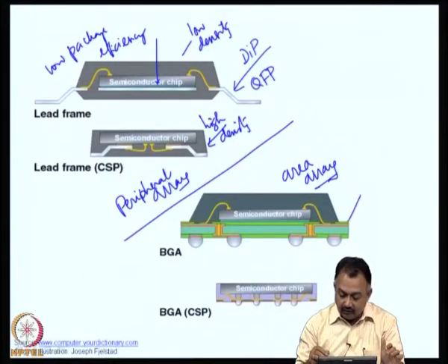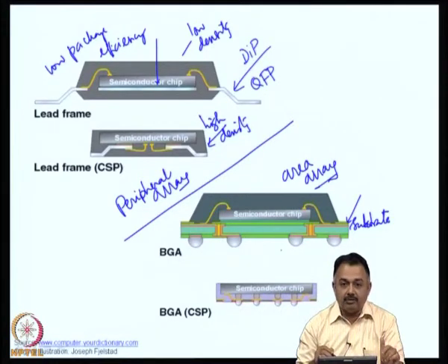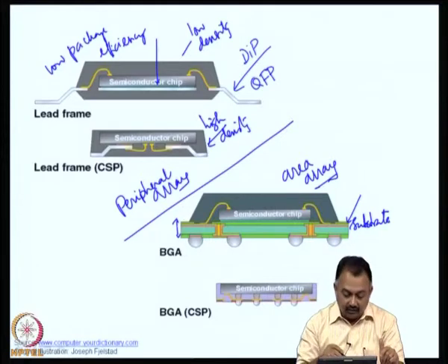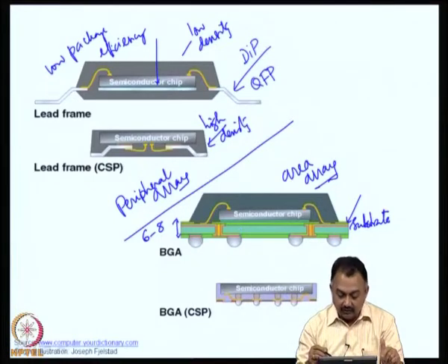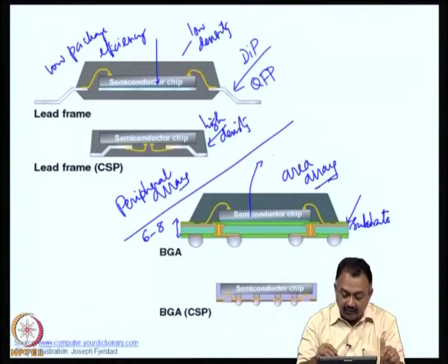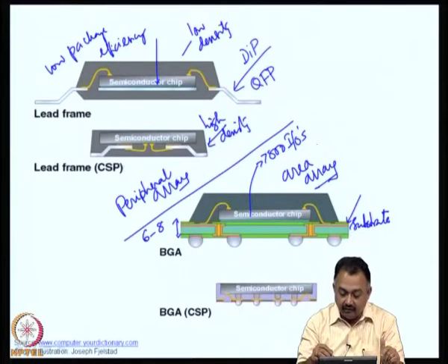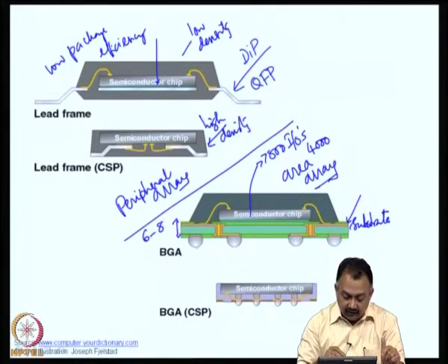Now, this one is a substrate on which the chip is mounted, and this can be a very high density substrate, typically using 6 to 8 layers of copper for interconnections, because you can expect this one to have greater than 800 IOs. Today there are area array packages having IOs as much as 4000. Okay. So, here the interconnections are established by these solder balls.